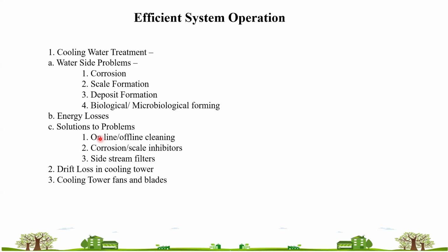In the energy audit, you need to be thorough about all the things happening around that factory, around that system. So if you are doing a commercial building, you need to understand why the building has to be pre-cooled, why pre-cooling of the building is mandatory. If you have Saturday and Sunday off, why on Monday do you need to keep your air conditioning on at 4 in the morning if your office is at 9 a.m. or 10 a.m.?